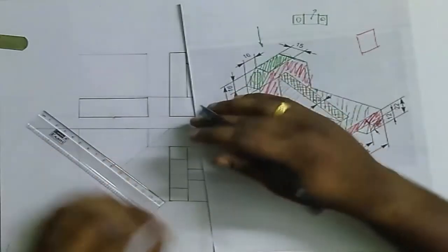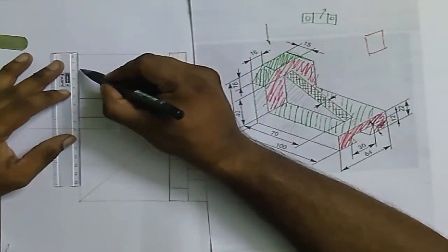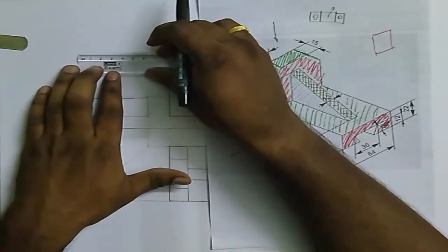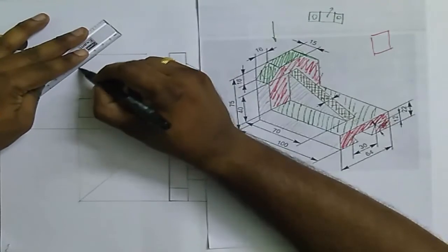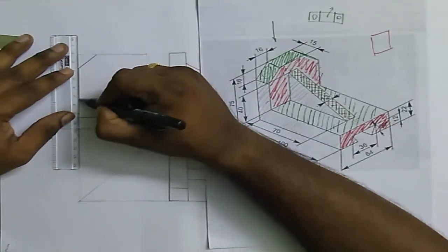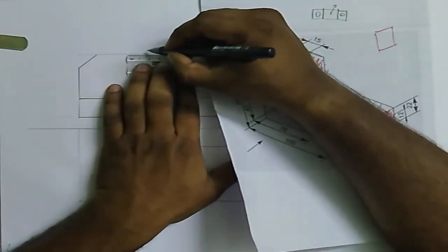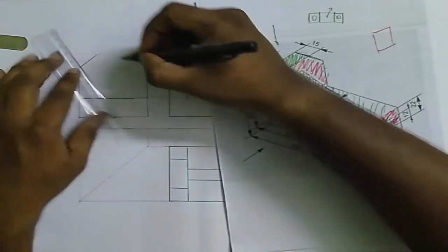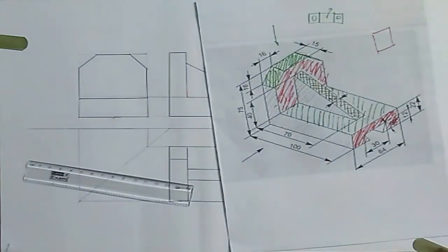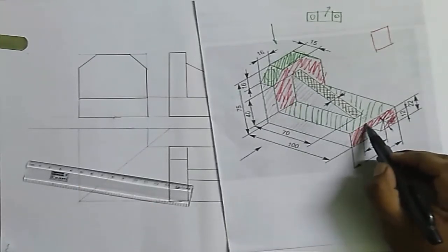Just complete this rectangle and then this height is 16 mm and this length is 16 mm. So from the corner point make a 16 mm point here and similarly from the corner point in the horizontal direction also make a 16 mm line. Then join these 2 points, you will get that chamfer line. Similarly here also make a 16 mm, so make it here, you will get that chamfer easily. Okay, that's all. This is my right side view.